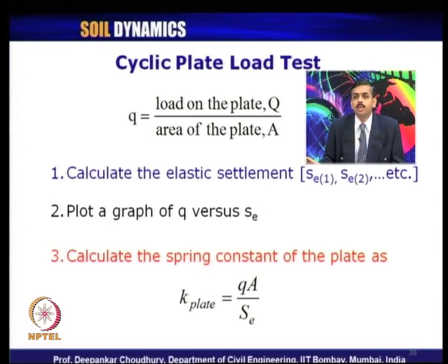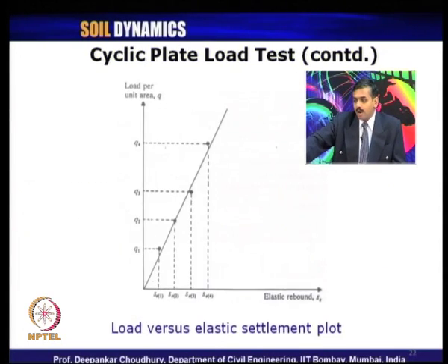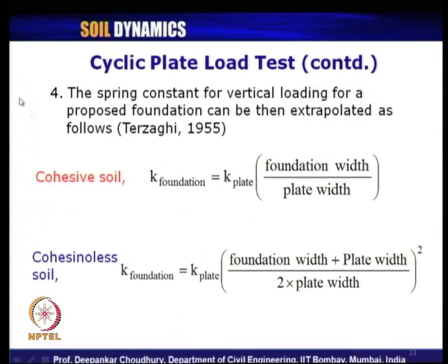The same thing that we have done for the static load test, here also for the cyclic load test we need to apply. So, let us see in what way we can compute the stiffness of our footing, because for any design we should know the stiffness of our footing material. The spring constant for vertical loading for a proposed foundation can be extrapolated from the plate load test, as proposed by Terzaghi in 1955.